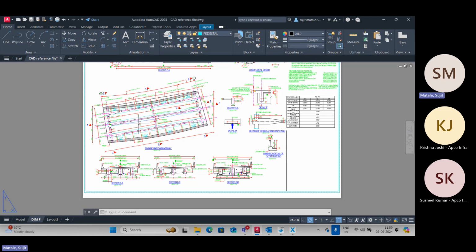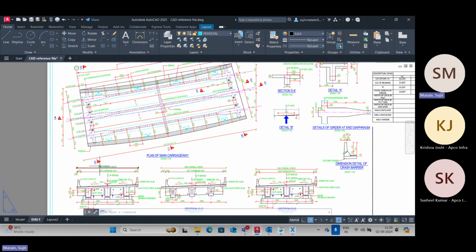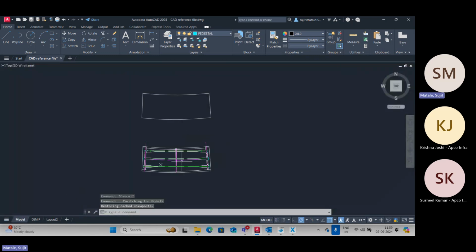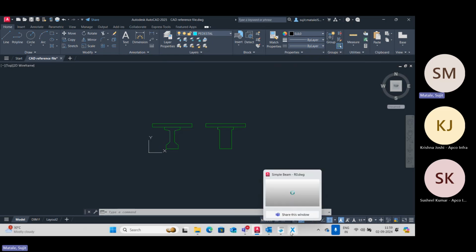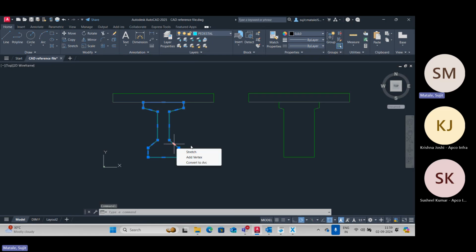Did you open this file, everyone? So did you see what geometry is? So this is a file that I received from one of the design offices. And what I did is I went to the model space and यहाँ पे हमारे यूज के लिए छोटा ऐसा एक बना के रखा है मॉडल मैंने। यहाँ पे ऊपर अगर जूम आउट करोगे तो यहाँ पे आपको क्रॉस सेक्शन भी मिल जाएंगे। इन क्रॉस सेक्शंस का इस्तेमाल करेंगे। क्रॉस सेक्शन का रीजन बना के रखना है हमेशा जब भी इंपोर्ट करना है। हाँ नहीं, एनक्लोज लाइन बनाना, पॉलीलाइन बनाना। Polyline या line connected. Line भी connected रहेगा तो फिर कोई problem नहीं. So it should be only enclosed.